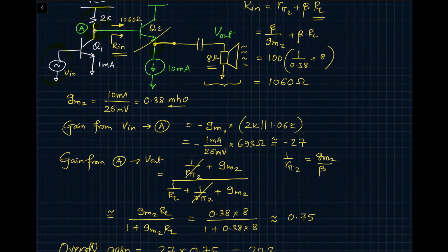Many times this circuit is also called a driver circuit. For example, you achieve all the gain that you desire using a series of amplifiers, a cascade of amplifiers, and then at the last point where we need to drive a low resistance, that's when you use a stage like an emitter follower, or we call it a driver stage, to finally drive the low resistance.